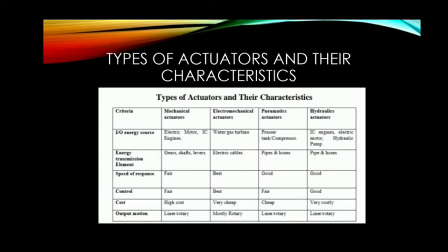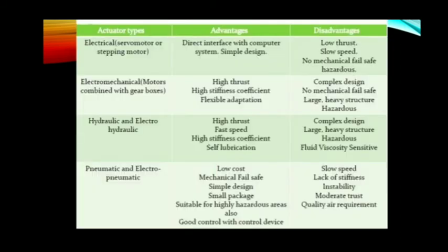Temperature switch. Temperature switches automatically sense a change in temperature and open or close an electrical switch when a predetermined temperature is reached. This switch can be wired either normally open or normally closed. Temperature switches can be used to protect a fluid power system from serious damage when a component such as a pump or strainer or cooler begins to malfunction.